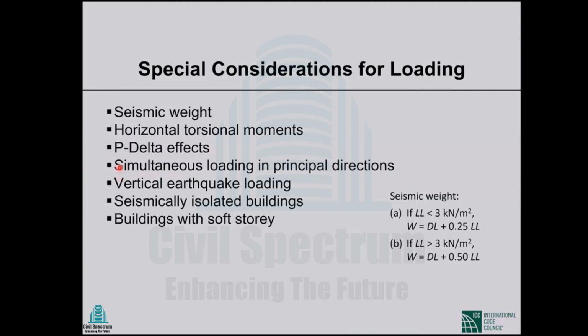This is very important: simultaneous loading in principal directions. In the previous version of the code, we used to calculate earthquake load only in the X direction and only in the Y direction, and then we had to analyze the two cases separately. But this time, when we consider load in the X direction, at the same time we have to consider 33% of the load of the Y direction simultaneously. In most of the cases.